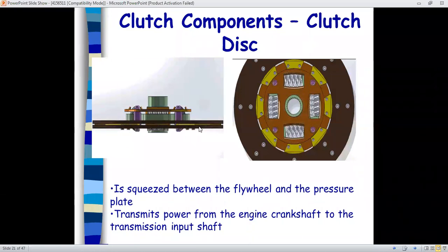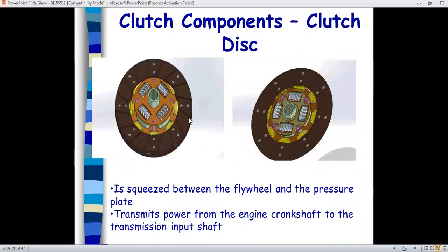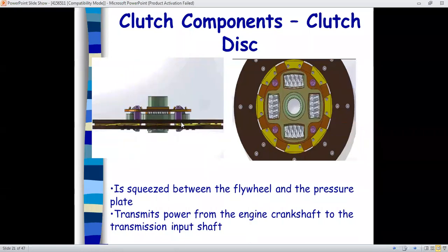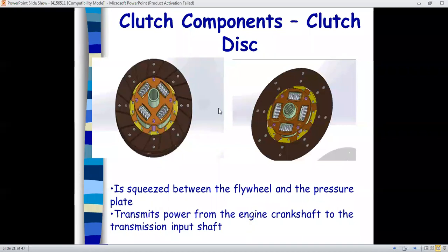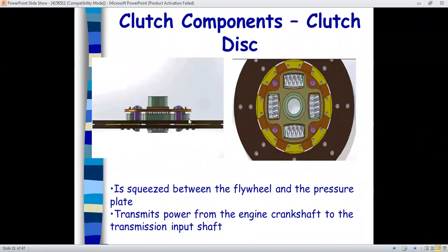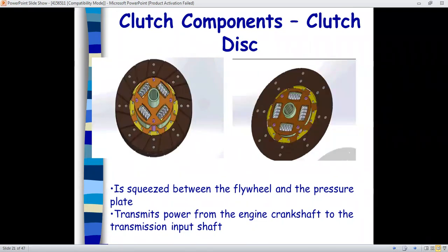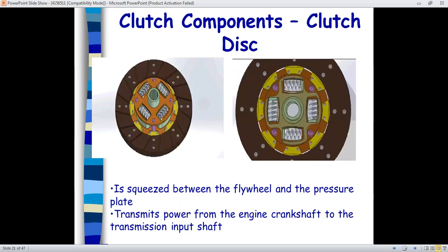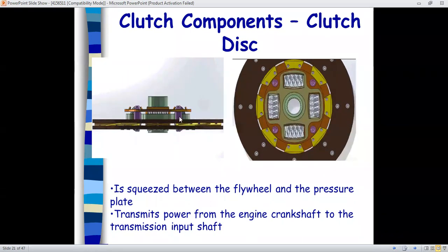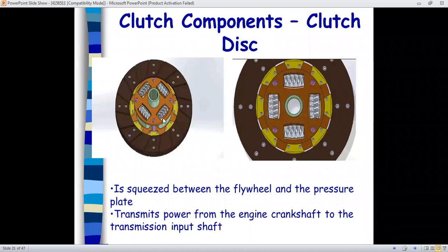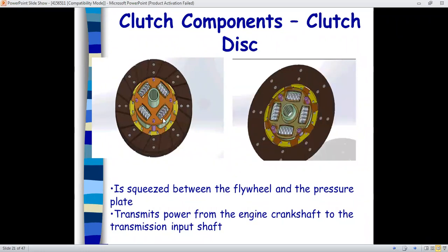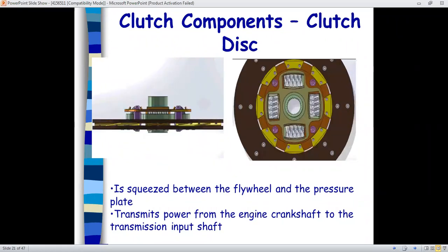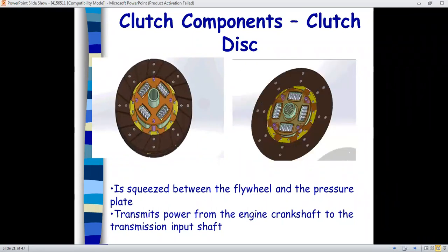So what happens? When the pressure is released, the spring is there, and the upper and lower plates are connected to the driven and driver shafts. When we apply force on the spring, it is pushed away and disengaged, disengaging the transmission system from the engine to the drivers.